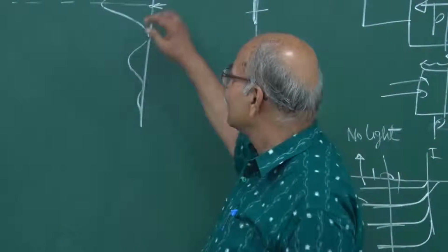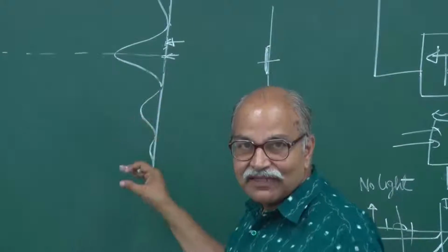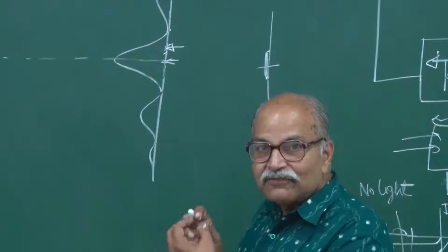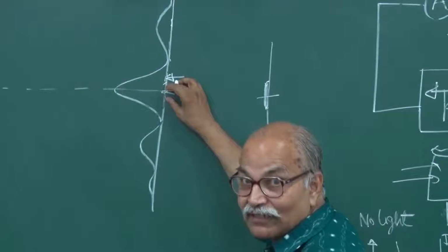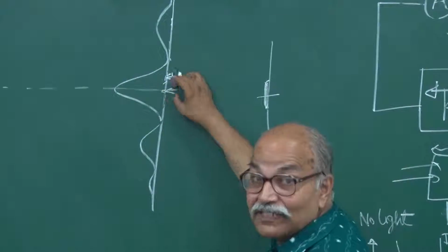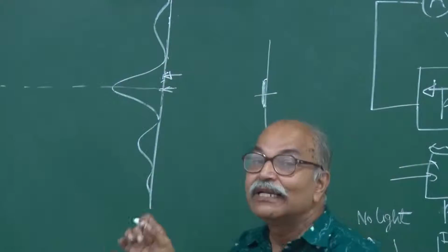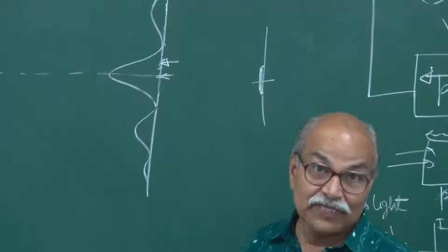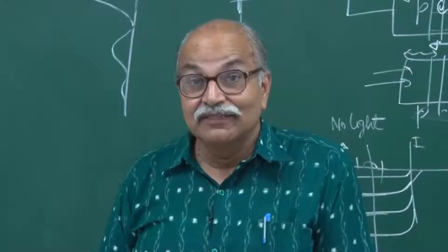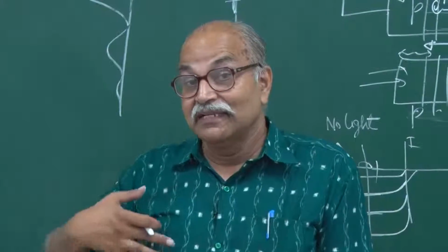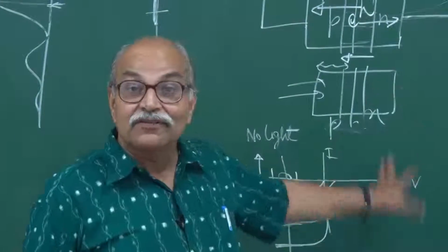Okay, as I said, in the room you will have some background light, so that will affect. Then when it falls on the photodiode, you have to check that it is rightly falling on that. So the orientation of this photodiode, if you shift from here to here and the orientation also changes, then there could be a problem. Then the photodiode can saturate, so that if the intensity is very high, then it is no more proportional. So that can also create problems.